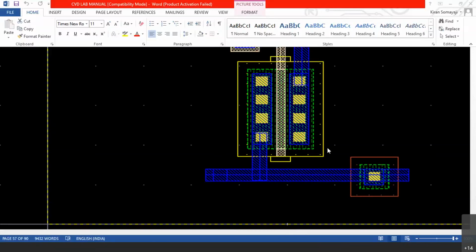Now again, there is a PN diode, right? Between this N-type implantation and the P-type substrate, there is a PN diode. That diode has to be reverse biased now. There should not be a leakage current in the body of the N MOSFET. So for that purpose, the body of the N MOSFET is substrate itself, P substrate itself. That should be connected to ground.